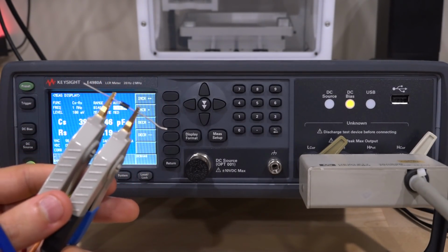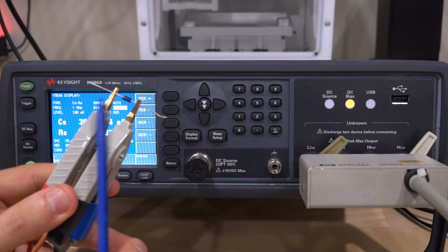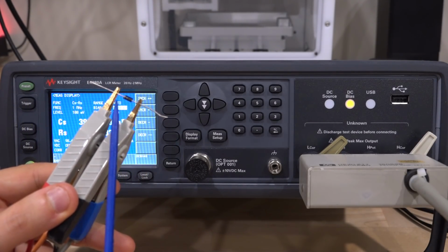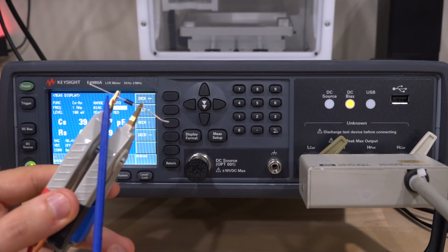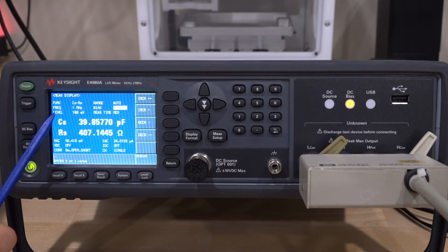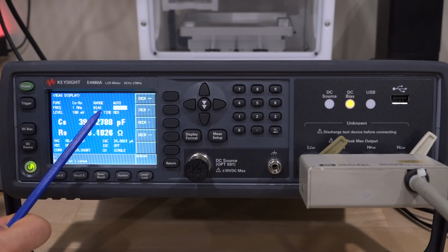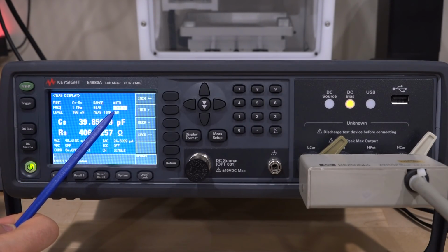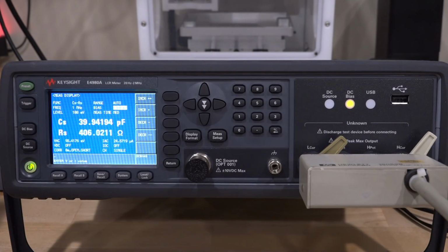Now if you look, what I'm measuring is actually a diode. So we have right now a PN junction here that's between these two, and we have to be careful when we measure an active device like this because you don't want to forward bias it by applying too much voltage across it in AC. So I've taken care of that by applying only 100 millivolts to the device. But at the same time, I also have a DC bias across the device too, of minus 200 millivolts. Now neither of these two values are large enough to turn on this device, but you can see we're measuring a capacitance of about 40 picofarad.